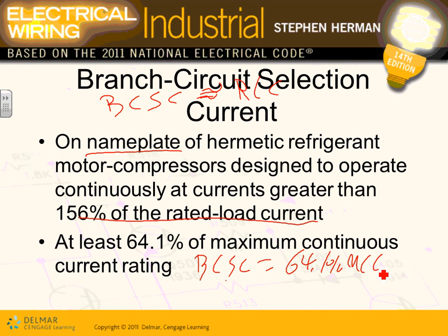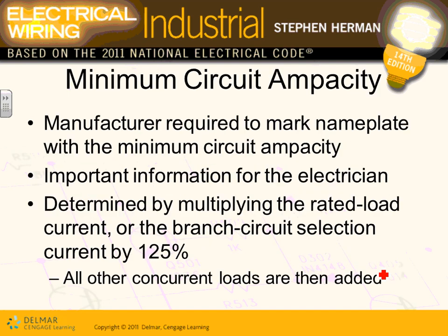So what's in it for you guys? Here's what we typically do. We use either the branch circuit selection current or the rated load current, whichever is larger, to size the fuses and the circuit breakers. Whichever is larger to size the fuses and circuit breakers.